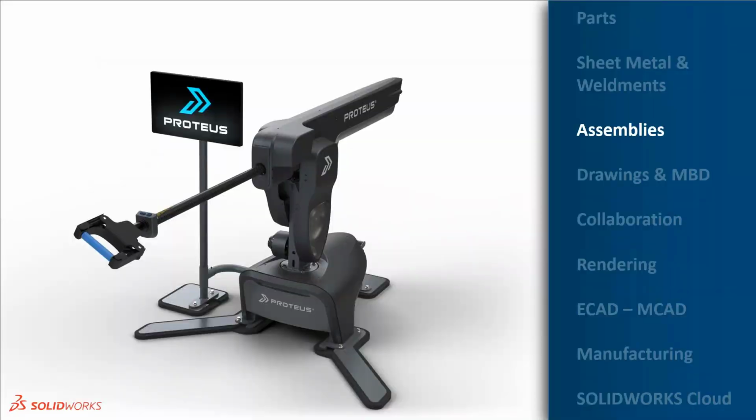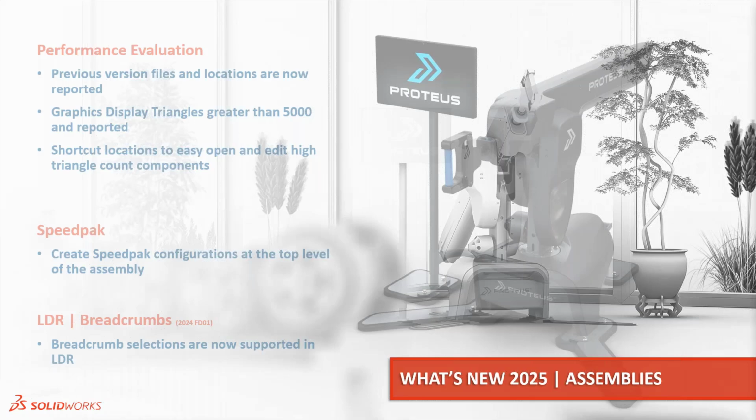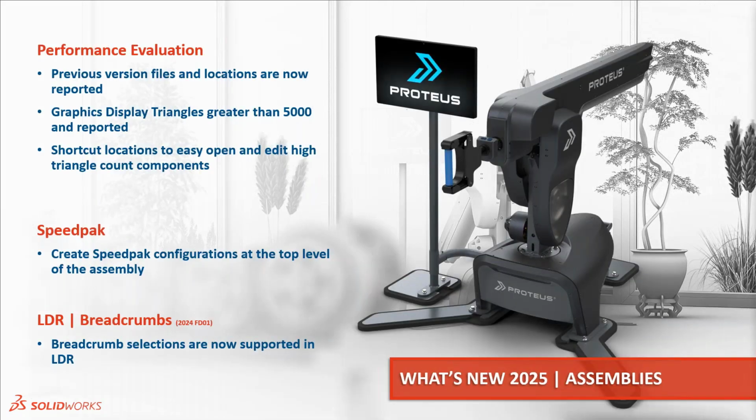Now we move to the next enhancement related to the assembly. In the assembly, in the SOLIDWORKS 25 version, there is some enhancement related to the performance evaluation. Now we are in the performance evaluation. The previous version files and their location are reported. Components with display triangle values greater than 5,000 are reported. A shortcut location is provided to easily open and edit the high triangle count components.